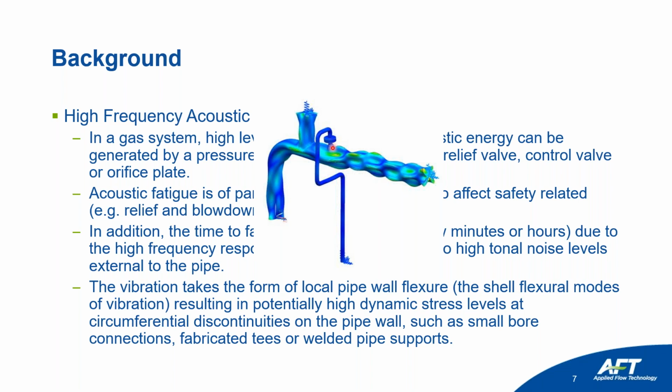And here we have a discontinuity that is a small bore connection. So it creates a shell vibration. And here, due to the high stress concentration factors in the connection, it can create failures in the small bore connection.